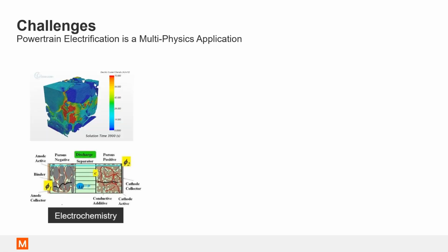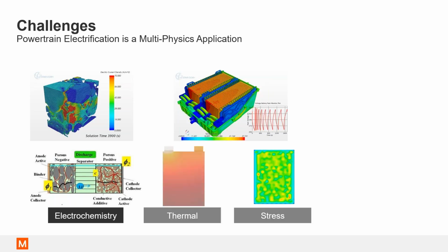So what are the different challenges that one faces with battery packs? I want to account for what would be the effect of tortuosity, or what is the potential drop across the half cell electrode, and what would be the effect of binders being added or conductive agents being added. So at the cell level, this is what cell designers would want to look at.